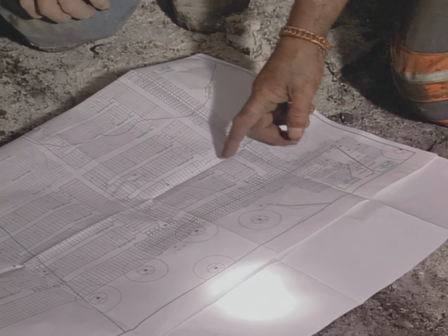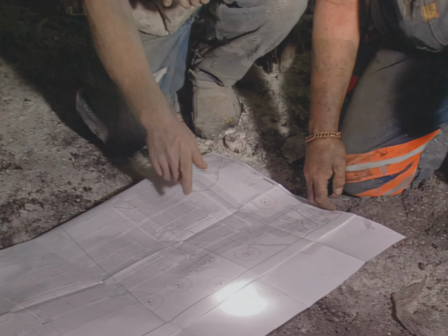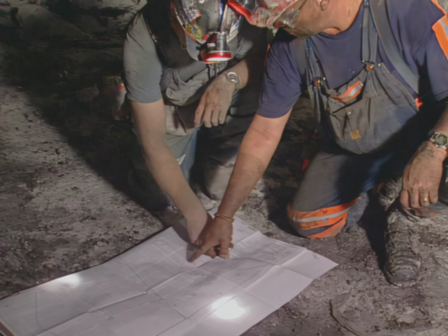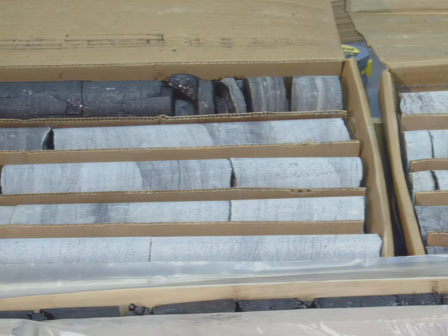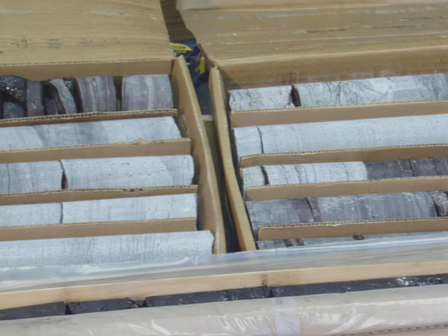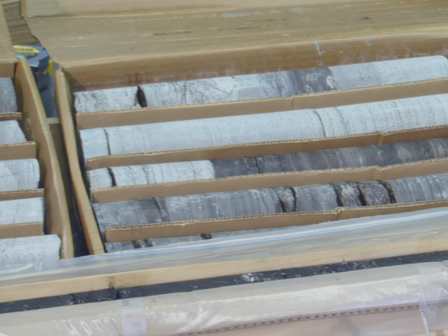You have heard over and over that you need to know your mine's roof control plan. Do you? Why is knowledge of the plan important to you? Let's find out. A roof control plan is not merely the brand or type of bolts that you put in the roof. To design a good roof control plan, you have to get involved early on and consider the coal bed that you'll be mining. You have to consider the depth of the coal bed into the ground. You have to, through core drilling, analyze the strata that lies above the coal bed and the surface. And all this figures into designing your roof control plan.